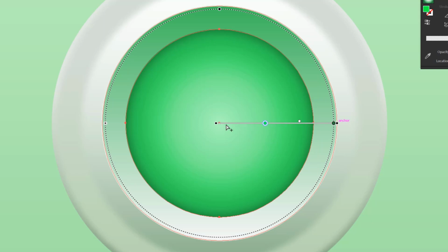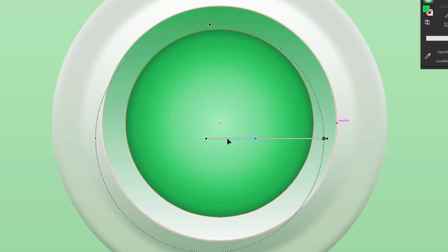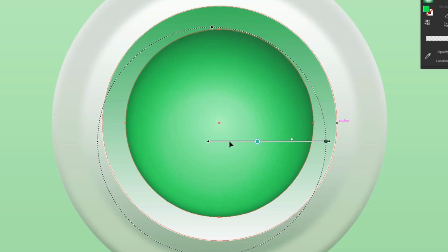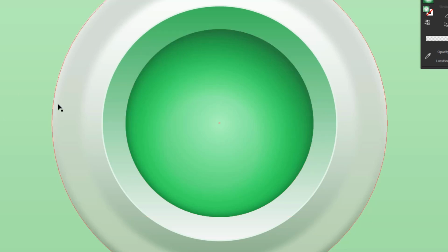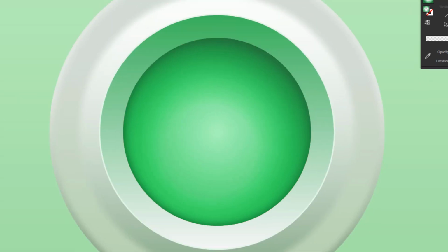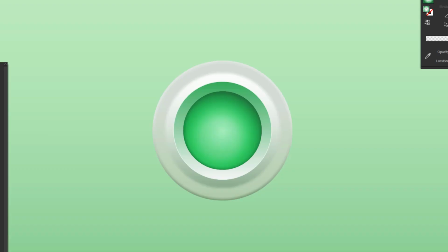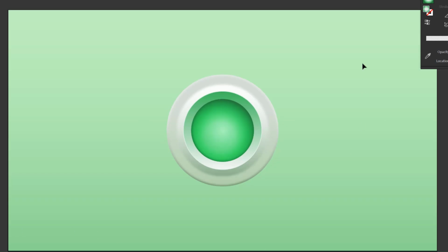After that, move your cursor again to this gradient slider line. Click and drag a little bit down until the center of the radial gradient is not in the center of the circle. So, the other part of the darkest color of this gradient comes out of the circle, so we'll get a bigger shadow area at the top, like this. The resulting shadow effect is thicker at the top at 45 degrees, so we can get a more natural depth effect. The deepest part of the compass icon will look more realistic by adding this second shadow.